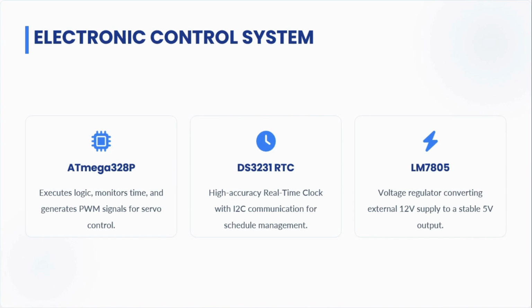Finally, for power management, we utilized an LM7805 voltage regulator. Our system is designed to receive an external 12 volt supply, and the LM7805 safely steps this down, converting it to a stable 5-volt output to protect our logic components.